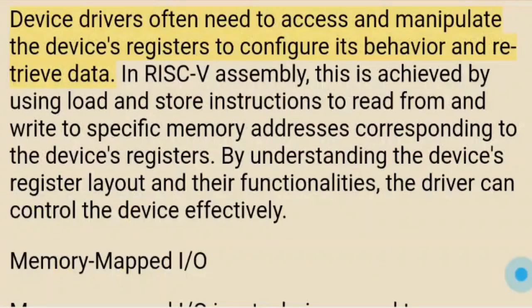Register access. Device drivers often need to access and manipulate the device's registers to configure its behavior and retrieve data. In RISC-V assembly, this is achieved by using load and store instructions to read from and write to specific memory addresses corresponding to the device's registers. By understanding the device's register layout and their functionalities, the driver can control the device effectively.